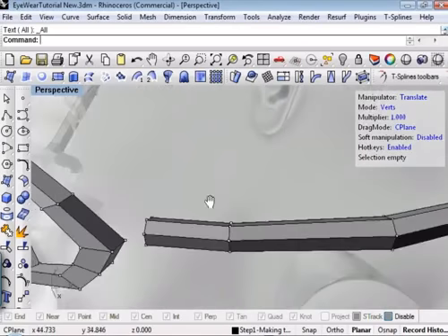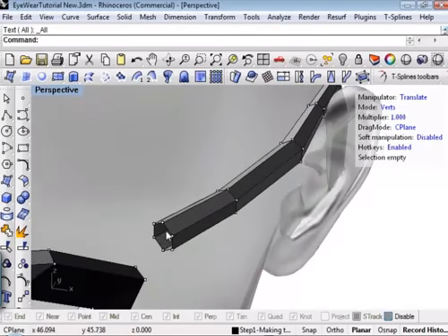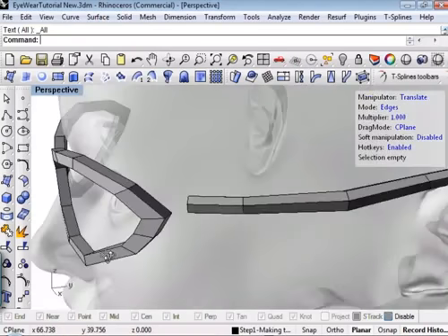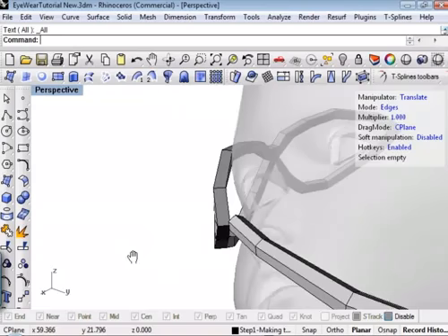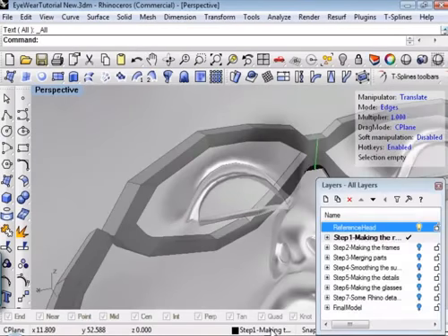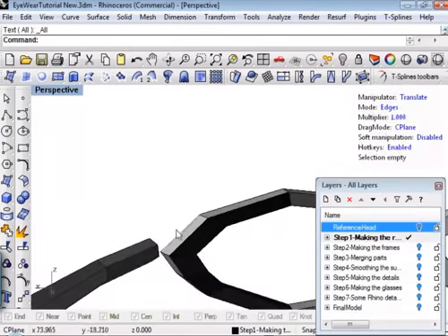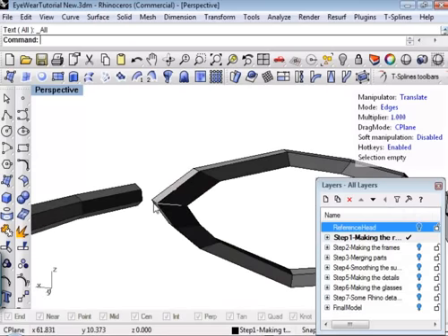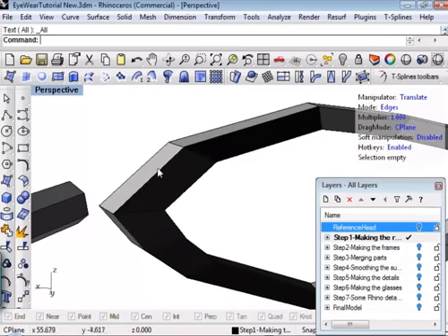And you'll notice that the opening on the edge of this model has 6 edges. 1, 2, 3, 4, 5, 6. So to make my life really simple, it would be great if I had 6 edges that I could connect into. Let me hide the head here. Well, where could I get that? 1, 2, 3, 4, 5, 6. Well, all I've got to do is get rid of 2 faces, right?